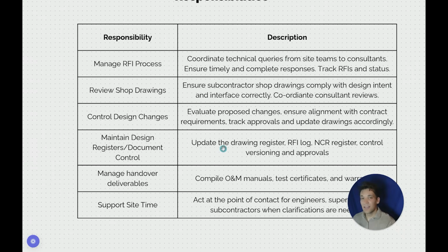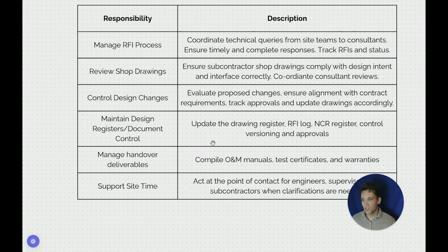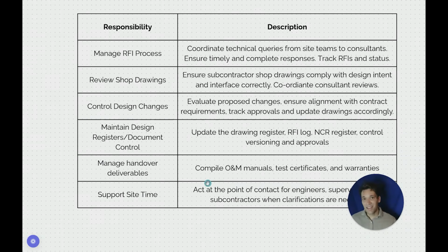They're maintaining the design registers and document control, so they'll update the drawing registers with any new drawings, RFIs. They'll control the NCR log, control versioning and all the approvals. They're managing design deliverables, so for instance the operations and maintenance manuals, test certificates and warranties. At the end of the day, they're there to support the design team, but also to control the design and again ensure that what we're building meets all of the requirements of the project.